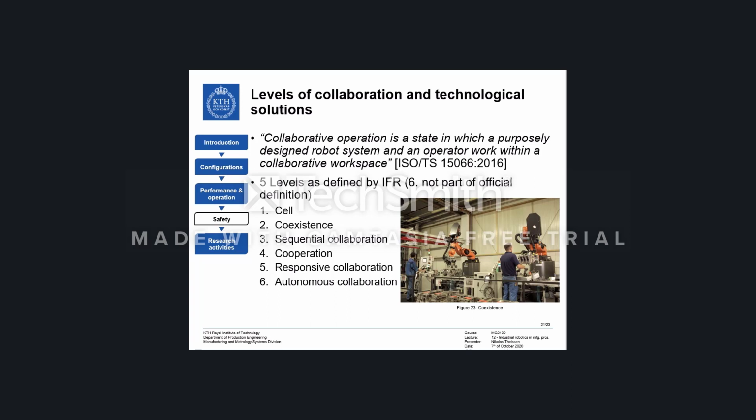Then there are position switches. A position switch is used to indicate where the robot is working right now. In traditional robots, there are position switches for axes 1, 2 and 3 to indicate whether the robot is entering the area or not. This is used for machine protection or for personal safety if the robot and the worker have the same workspace as in the coexistence cell layout.